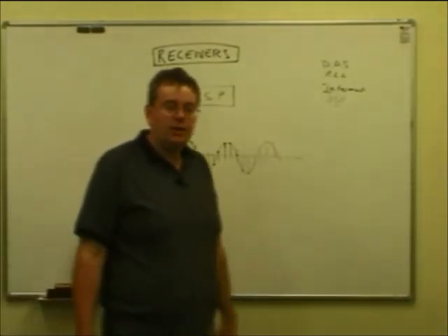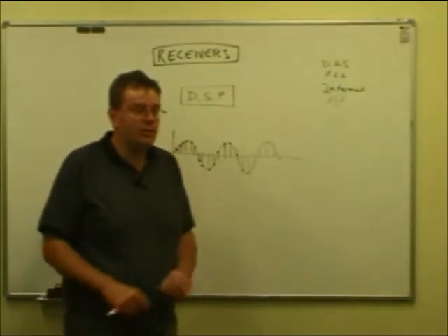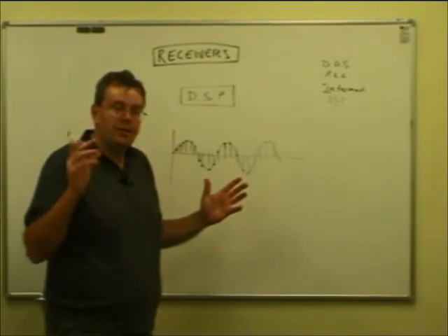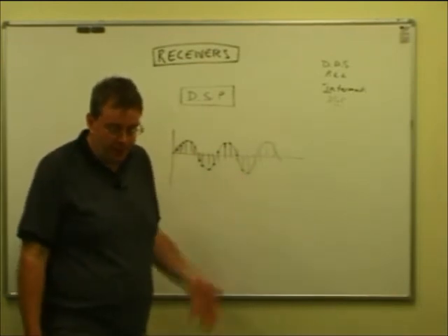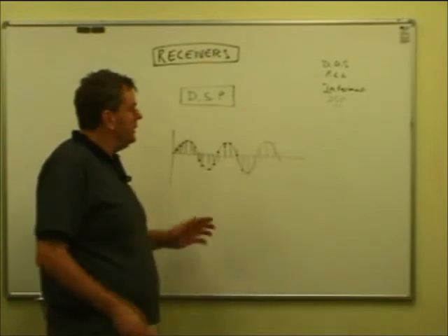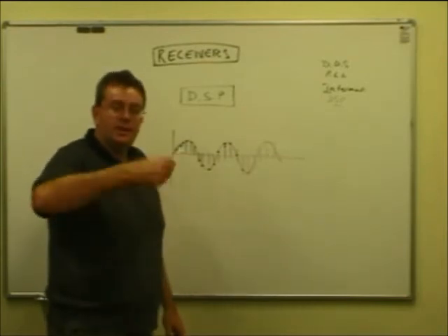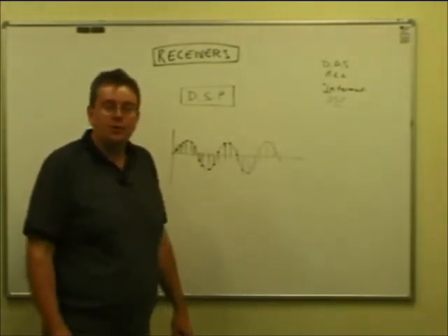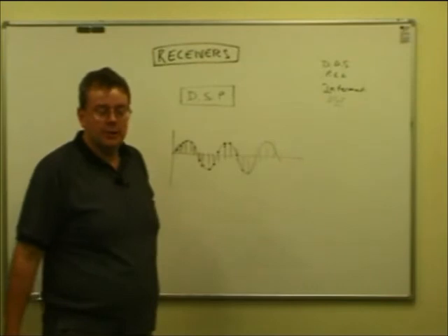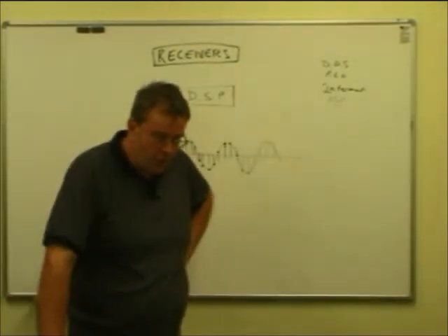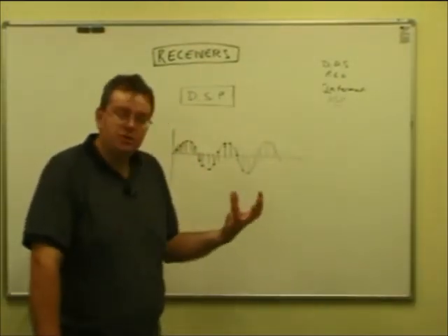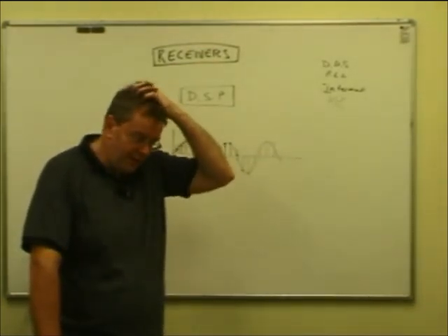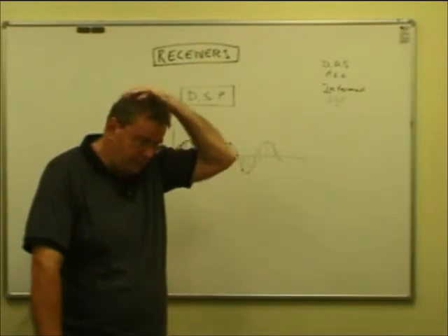Once you've done that, you've now got the ability for a computer to analyze it, and it can do very clever things. Maybe you've got an annoying whistle, you know, beep, going in the background from another signal nearby, often called a heterodyne or a whistle. It can look for a regular repeating number pattern and remove it, subtract it from the signal, and you push the notch filter function, it's called, bang, it's gone. It can do any other sort of noise. The modulation is going to be a fairly random sort of phenomenon, but anything that's regularly repeating itself and being a pain in the background in a noise fashion, it can get rid of that.